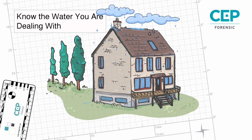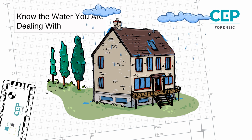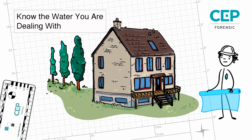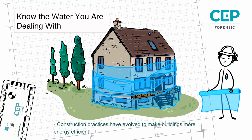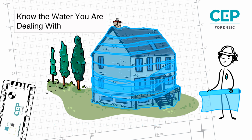Controlling rain entry above grade and groundwater entry from below grade have been the focus of builders and designers for decades. Air leakage and vapor diffusion have received far less attention. The push for energy efficiency has been rapidly evolving construction materials and methods, resulting in tighter buildings. However, these methods, which are meant to perform better energy-wise, are more sensitive to air leakage than older constructions.